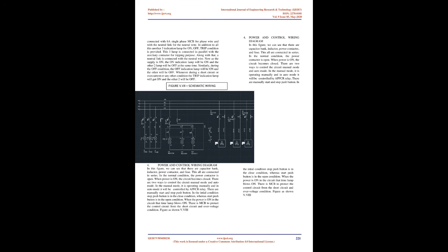There are 3 switch fuse units connected to the supply. The purpose of the SFU is to provide protection to the capacitor banks from fluctuating conditions. There are 3 power contactors provided. During an overload condition, when excessive current is passing through the circuit, the normally closed contactor will be opened and protect the capacitor banks. Here the detuned reactor is coupled with the capacitor as shown in the figure.